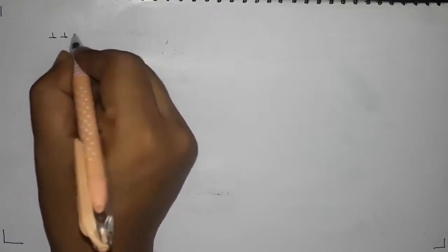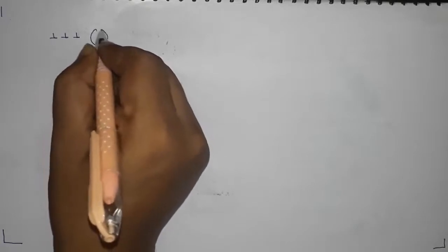Okay, so they are barriers to themselves, but before we go to the dislocations acting as a barrier for their own movement, the theory which was given to describe strain hardening said that dislocations pile up at the barrier.